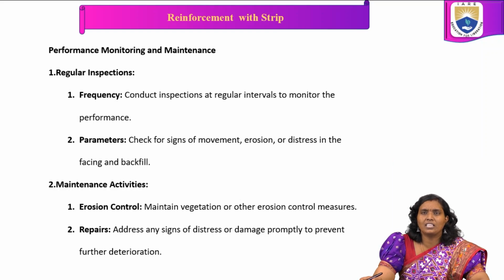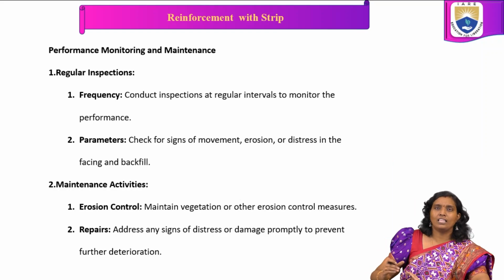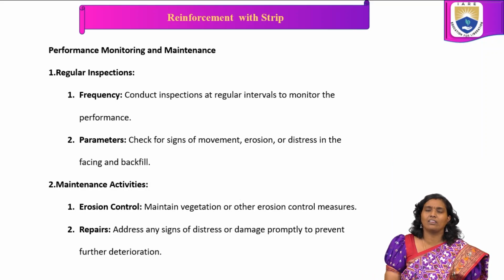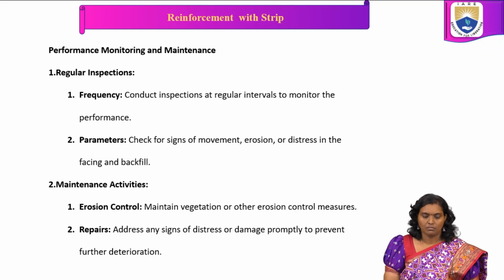In these parameters, check for signs of movement, erosion, or distress in the facing and backfill. Whenever we are checking the signs of movement, erosion condition, and distress in the facing and backfill, once we conduct these inspections at regular intervals, the monitoring gives better performance.